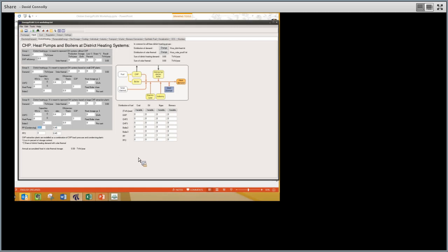So we include, let's say, coal power plants, combined cycle gas turbines, biomass power plants, and things like that. The typical way that we use PP2 is if we have some really inefficient peaking power plants that are not used very often during the year, but they might have an unusual fuel distribution, a very low efficiency, and a very high operating cost. So a typical way that we would use PP2 is if we have something like 300 megawatts of peaking plant. It might have a very low efficiency because it only comes on for a few hours, something like 20%, and it might consume something like oil.